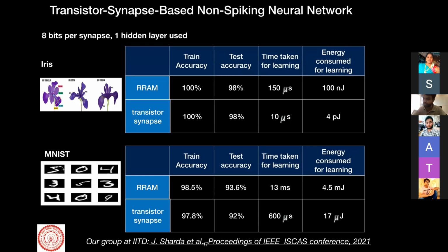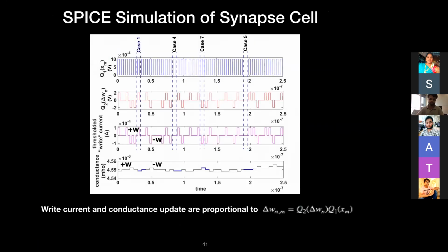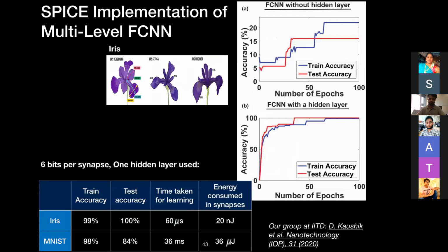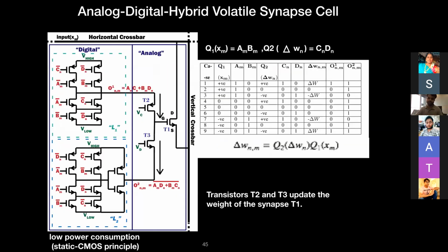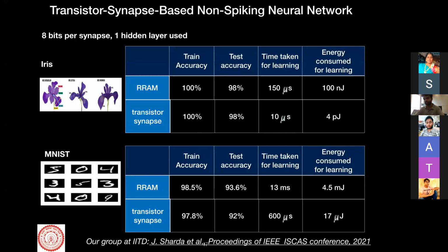Why? Because it trains very fast. On the other hand, the moment I do a convolution network, this system fails. Why? Because the training time is much higher, and by that time the weight values are lost. So what I'm trying to say is that the result I showed earlier for spintronic synapses on the MNIST dataset cannot be extrapolated all the way to CIFAR-10 or CIFAR-100 for convolution networks. That is not the case with these devices. Make sense? Yes, sir.